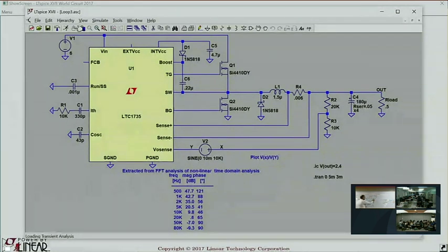All right, the output is divided down. We compared the divided version of the output to the reference voltage. The difference between the divided version of the output and the reference voltage is the error voltage, which is amplified to be a current flowing out the pin where we started. However, it is not the current flowing out of the error amplifier that sets the peak inductor current. It is the voltage on the output of the error amplifier that sets the peak inductor current. So to complete going around the feedback loop, we have to read out this current to a voltage.